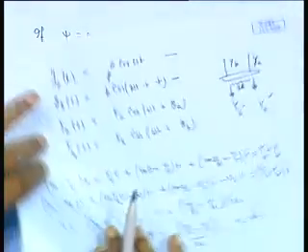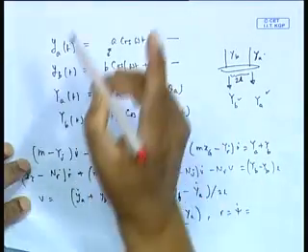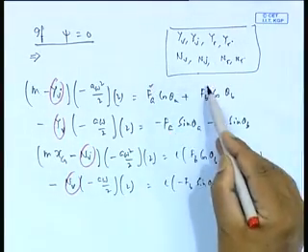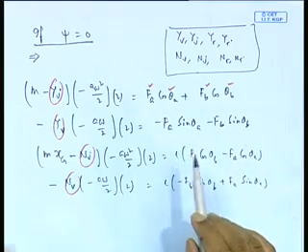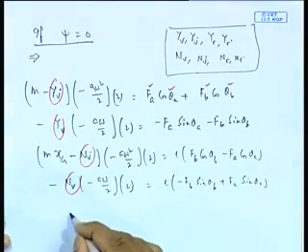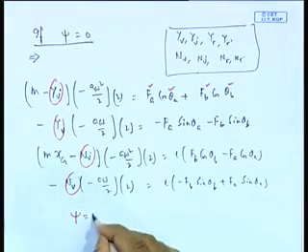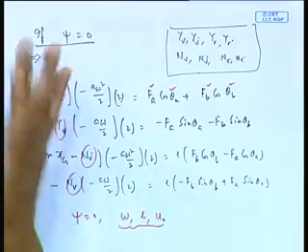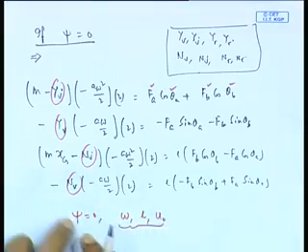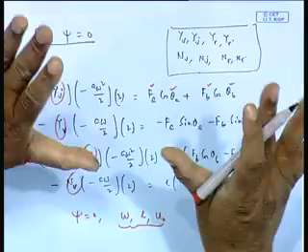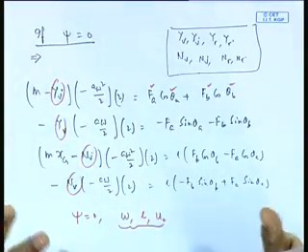Therefore, when I do the experiment with psi equal to 0, that becomes a pure sway test. You have the 4 equations, I can solve it. I am measuring Fa, Fb, theta A, theta B, 4 unknowns I am measuring, remember. What did I input? I input psi, in this case psi was 0, but I have omega, I have L, I have U0. These are given values. So for a given value of this with psi 0, I measured Fa and theta A, 4 unknowns, and the 4 equations I can solve for the 4 unknowns.